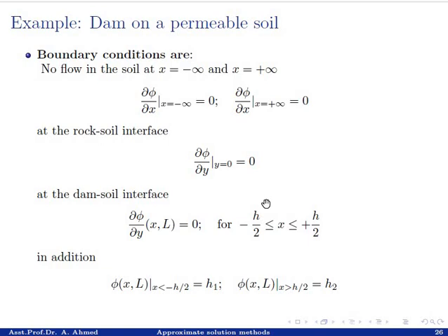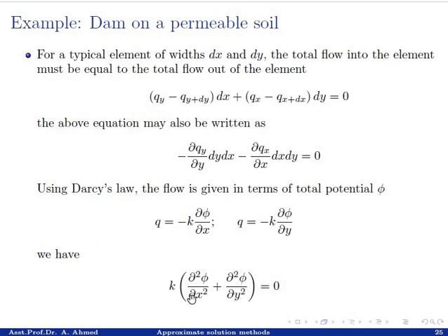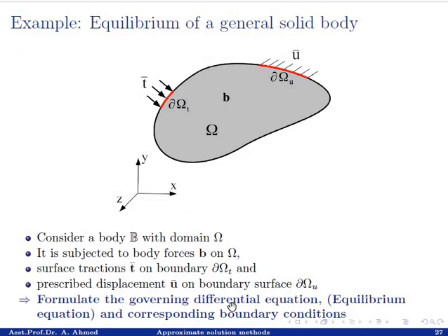So these are the boundary conditions that can be used in addition to this differential equation for the solution of flow problem in the soil. So all these equations describe the seepage flow in soil medium. So this is now the mathematical model for the seepage flow in a soil.